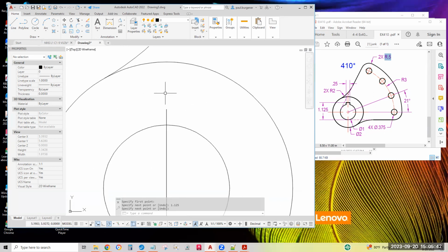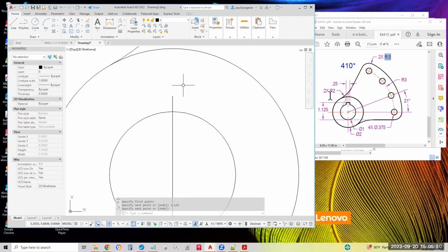Now, if we learn the move command, I can just draw a 1/4 inch line and move it from its center point to that end point. But that's next week, so we have to do a little arithmetic. Half of 0.25, 1/4 inch, is 0.125, or 1/8 of an inch. So let's draw a 1/8 of an inch line both directions.